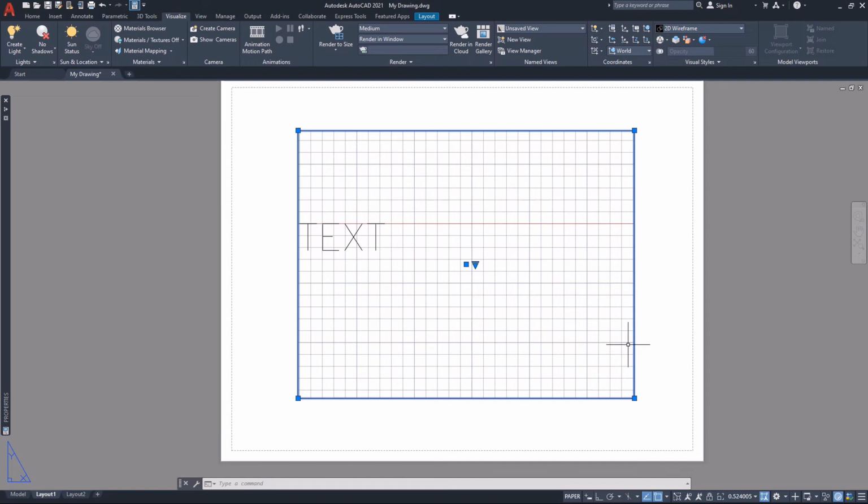It is always highly recommended that once the user's chosen objects are centered in a viewport window and the appropriate viewport scale is assigned, to lock the viewport window to prevent any undesired changes. Note that the current viewport scale factor is a seemingly random decimal factor.